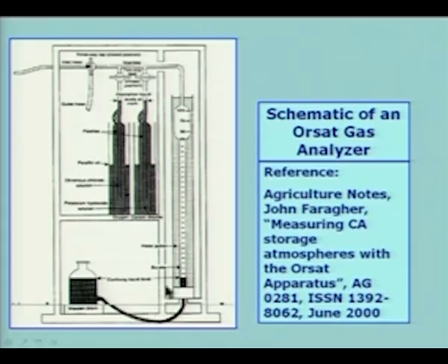Therefore, all the gas which is present in this is expelled to the atmosphere first by opening it to the atmosphere, then close the valve and open it to the inlet port, and then you lower the liquid level to the original level. So, what will happen is that the sample will be drawn into this, because as you move the liquid down, this vacant space which is created will take the sample, and the sample will fill this.